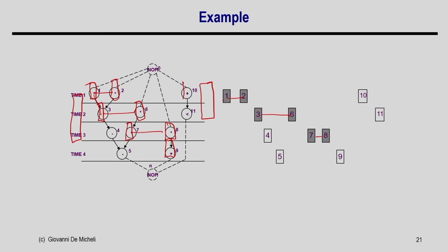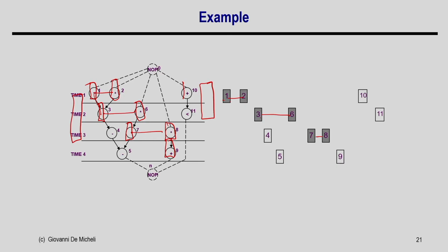These are my intervals, which satisfy the edge requirement of the interval graph. So, this is how I argued that once I consider a graph for only a single basic block, my complete graph is an interval graph and I can construct the corresponding intervals easily from the schedule, and its complement graph is nothing but a comparable graph, which I have already shown. So, I can efficiently solve the graph coloring problem for this graph in polynomial time, and for that there is a very well known algorithm called the left edge algorithm, and I am going to cover that algorithm in the next class. Okay? Thank you.